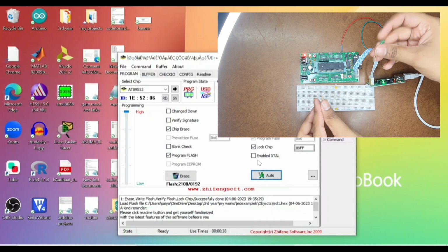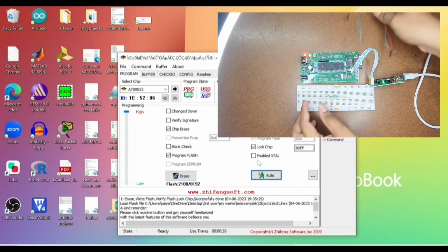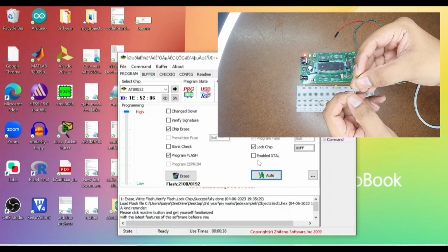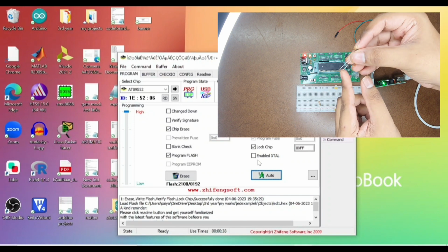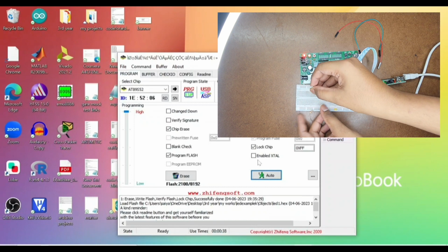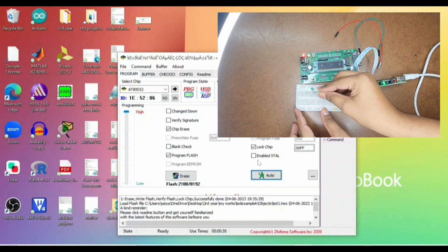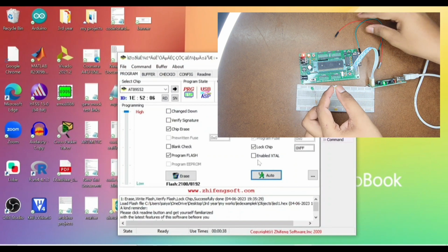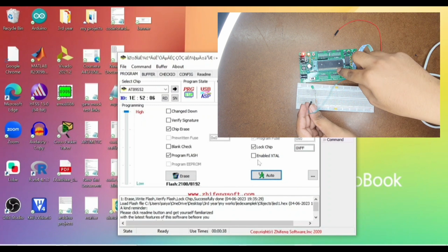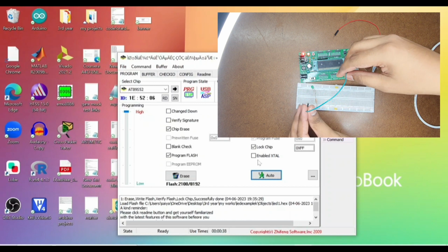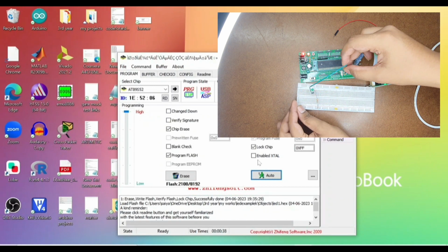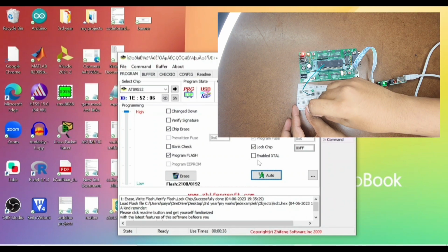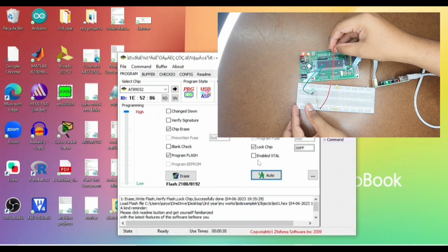Now you take a breadboard and take your resistance, LED and two wires. You see that an LED has a longer lead and a shorter lead. Longer is the anode, the positive side, and shorter is the cathode, or negative side. First connect them like this. The negative side of the LED, you connect to ground. Now take a wire, and as these have a male header pin, I will be using a male to female header wire. Connect the positive end of the resistance to pin 1.0, and connect the negative terminal to ground here.